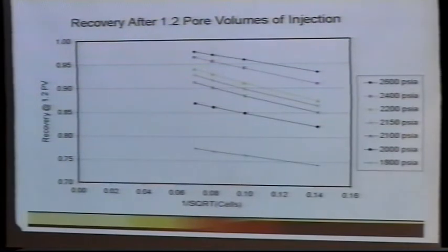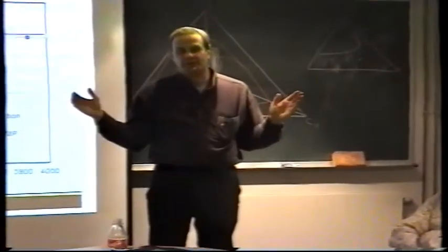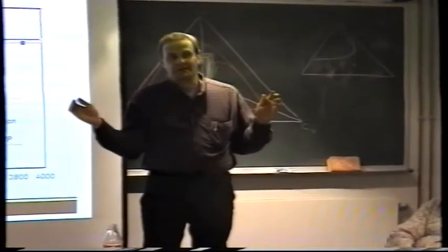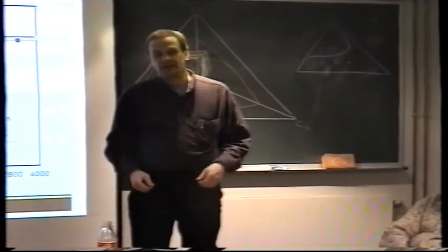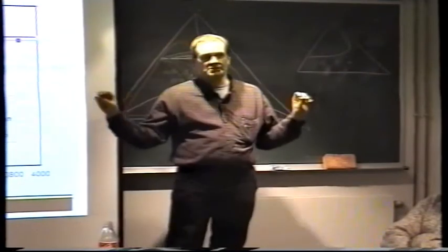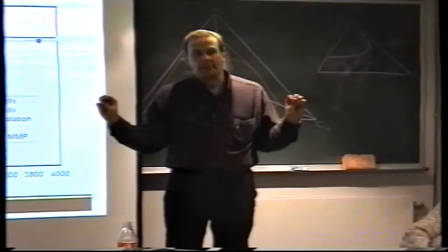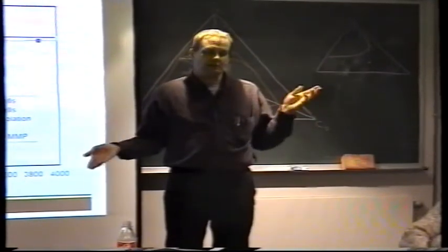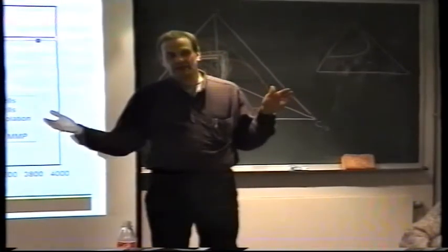One more question. Is the pressure a fixed pressure difference, or else the pressure at the front? In the simulations, you can use basically an infinite permeability, which means you have 0 pressure drop from one end to the other. So the whole slim tube, in the simulations, is at constant pressure. In the experiments, there's probably about a 5 to 10 psi pressure drop from one end to the other.